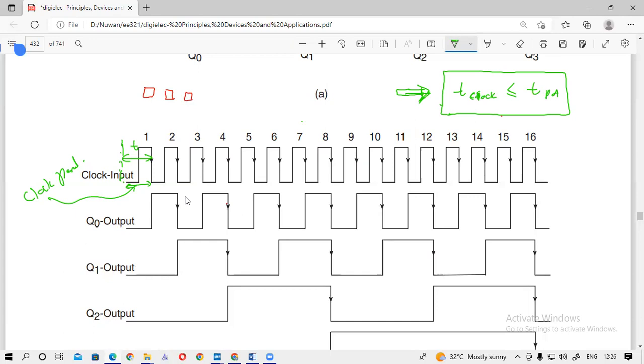So what I told you is that if any delay happens, there is a propagation delay, no? Here, there should be a propagation delay. Let's say the propagation delay is up to this level, a very few nanoseconds. So your output signal will be shifted somewhat like this.